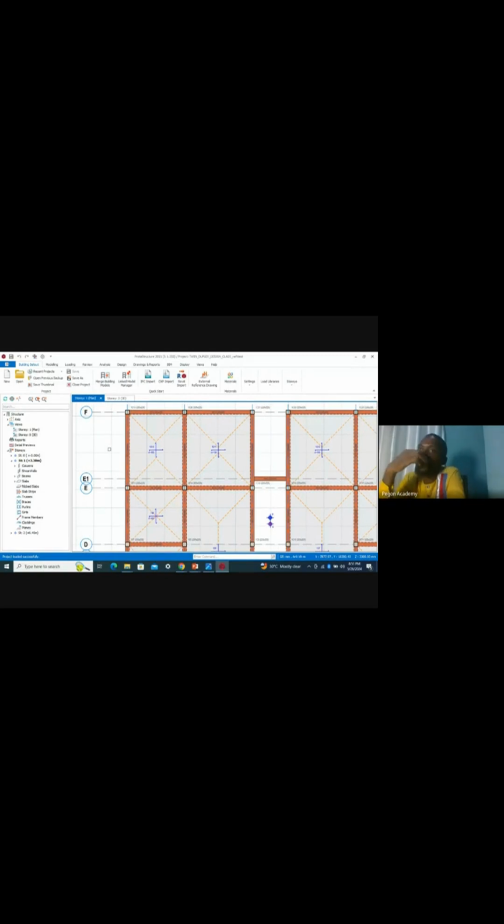Now, these lines you see here, they are called yield lines. Let me quickly explain what they mean. Now, you know that if you are designing a structure, like I said earlier, the loading is the most critical part of structural design. You have to get your loading right. The loading simply is transferred from the roof to the roof beams, from the roof beams to the columns, from the columns to the foundation, right? So it is actually a complicated process.